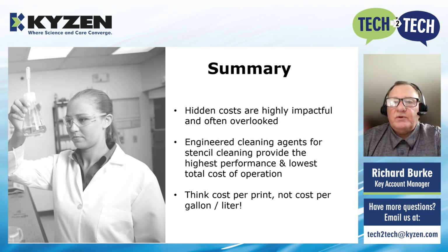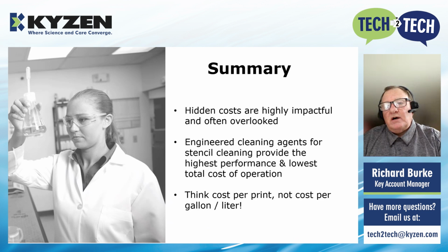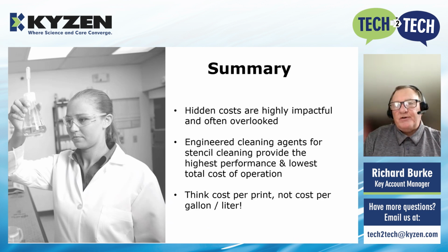highly impactful when it comes to the overall process costs. And these hidden costs are often overlooked. We often focus solely on the cost of the cleaning agent that we're using. Engineered cleaning agents for stencil cleaning provide the highest performance, but also the lowest total cost of operation. And I would leave you with this. I think the most important thing is to really think of it in terms of cost per print, not cost per gallon or liter.